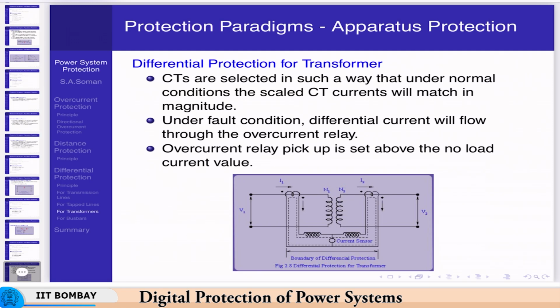Okay. So here you see that unlike in a transmission line, a transformer has a winding which will change not only the voltage levels but also the currents. So depending on the transformation ratio, N1 I1 is equal to N2 I2, the ampere turns will be the same, so the currents will also be transformed. So on the low voltage side, you will have a higher current.